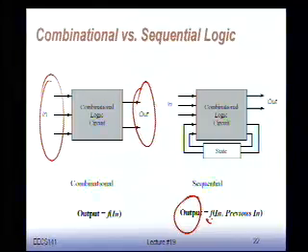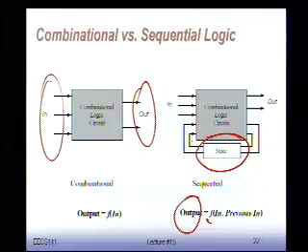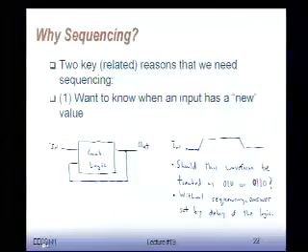But you already see that the registers in that filter help you to remember previous values of the inputs. Now, in order to do so, we have to have something that can store a value and remember it into the next clock cycle, which is called a flip-flop, or a register, or a latch, depending on what you're talking about.